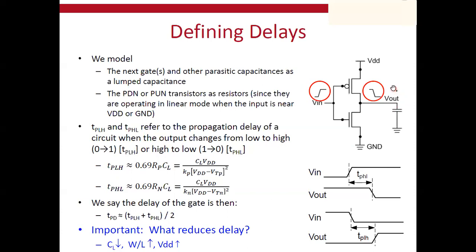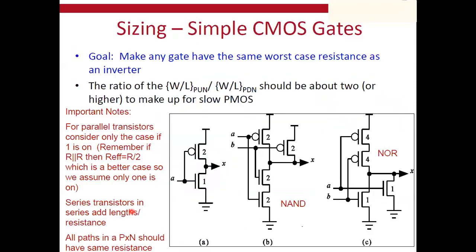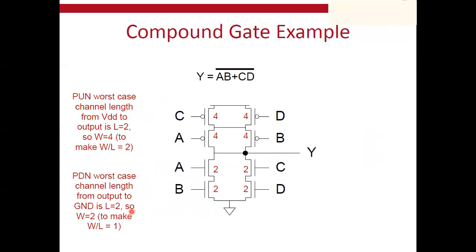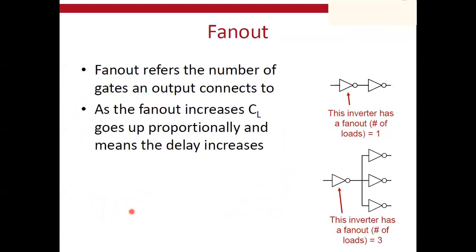And from the output perspective, you have this output capacitance that affects the tPLH and tPHL values, and the higher the fan-out, the higher the tPHL value, and generally then the higher the propagation delay, which is, of course, a problem. So this is one type of delay that you can see in your digital electronics IC, but there are still some